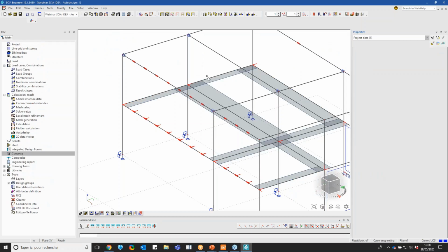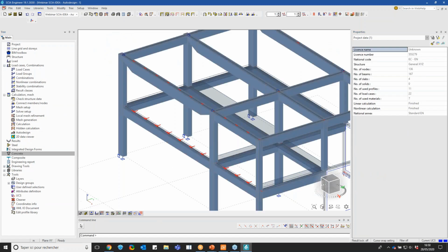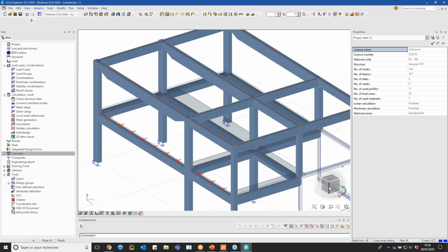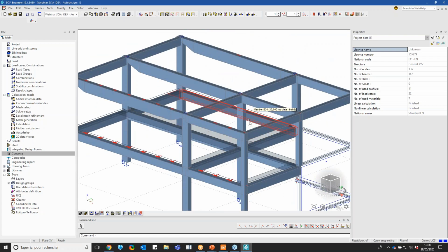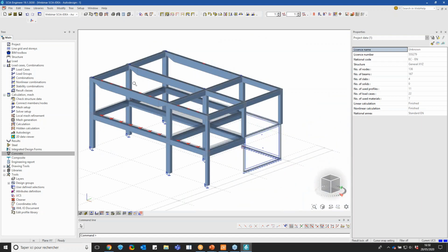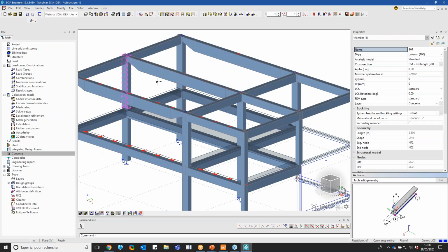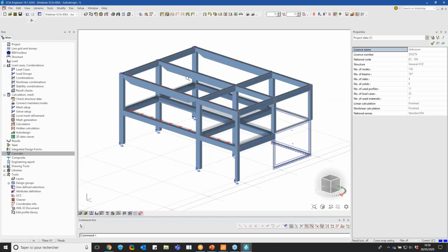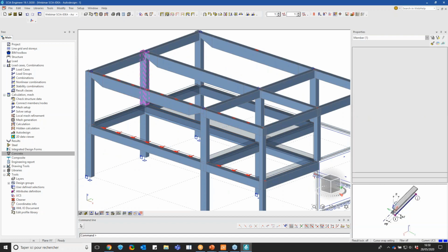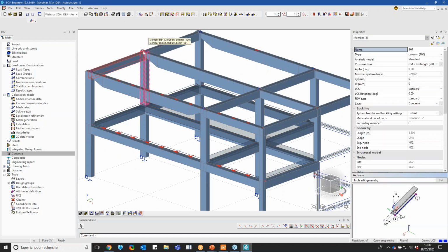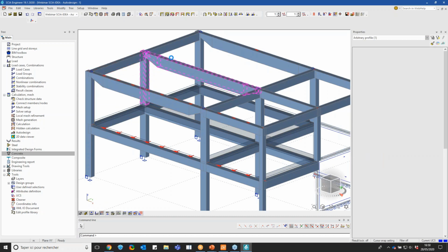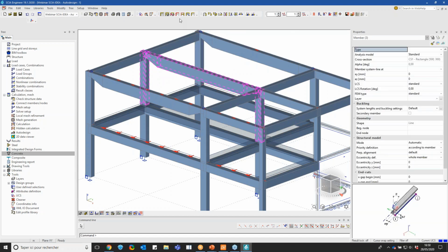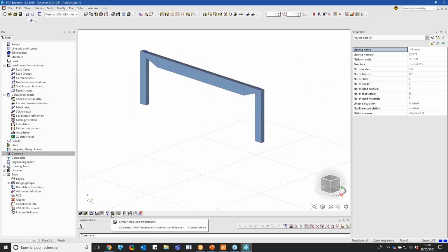In any case, what I want to show as well is how to export this variable beam to then be analyzed in StatiCa concrete. This is our last topic. In this case, I can either export the whole concrete structure, the whole structure as well, to perform, for example, other types of analysis of some nodes or some other type of rebar if I want to add them, or I can just export a part of the structure to show you how it works. In this case, I just export 3 elements.